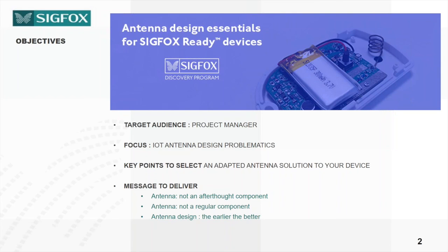And finally, I wrote antenna design, the earlier the better, which means that the earlier you take the antenna design into consideration, the better performance you can expect. If you start the antenna design too late in your device design or implementation, you might get some trouble to reach high radiated performance.